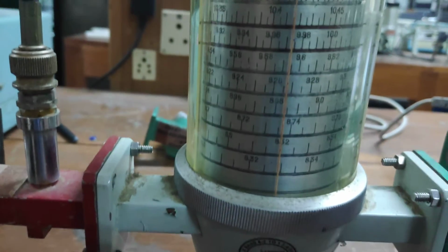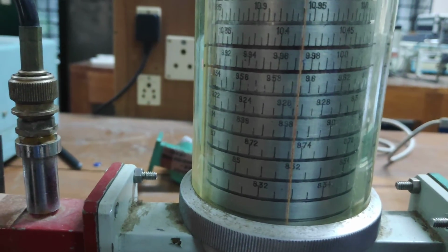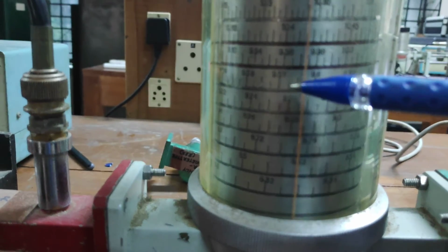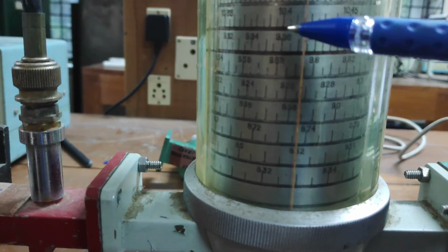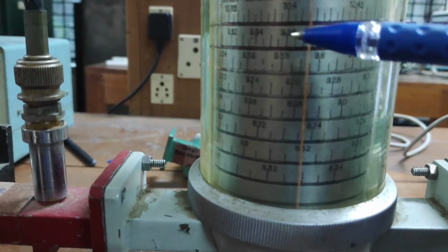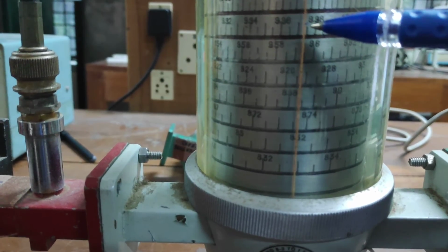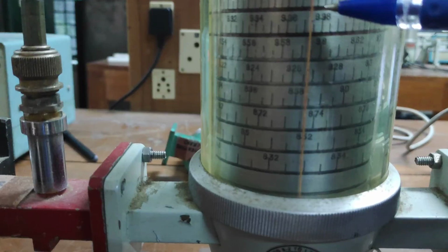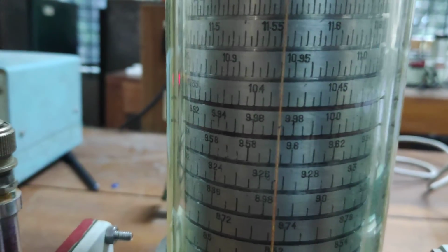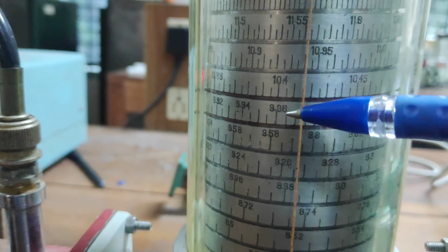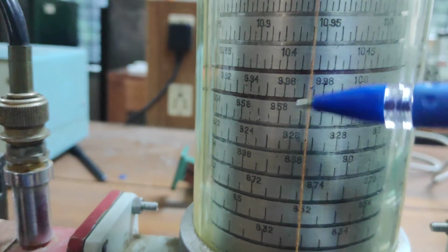That means at this point, this tuner is tuned to a frequency between 9.96 and 9.98, and the middle is 9.97. So this one is indicating 9.97 gigahertz. Oh, sorry, my mistake. Sorry for this. Here it is indicating